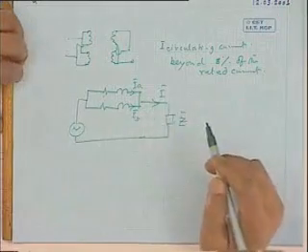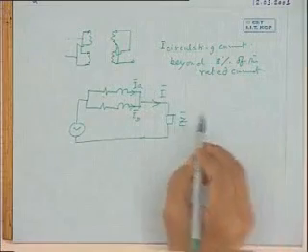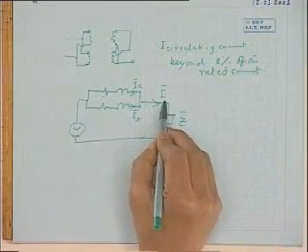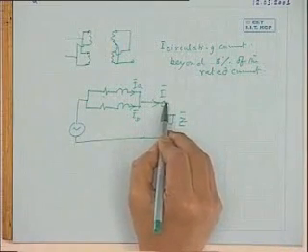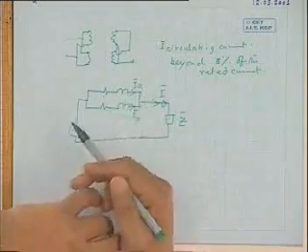Suppose the magnitude of impedances are inversely proportional to their KVAs. It will ensure that whenever there is some load current delivered to the load, the currents will be divided in the inverse proportion of their KVAs. That is what we want. That is, whichever transformer is larger KVA rating, it should share more current than the other. That is what we want.